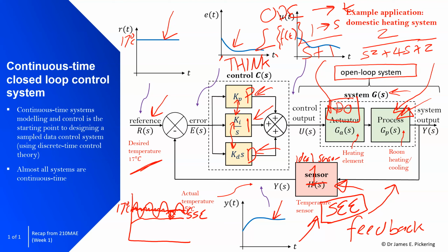So it works in a cycle continuously, and the whole idea is to try and achieve this reference by measuring and configuring your controller such that it can compensate for there being an error, and then your actuator enabling you to actually make that change based on the error. So the change that the actuator makes here is a function of this error.